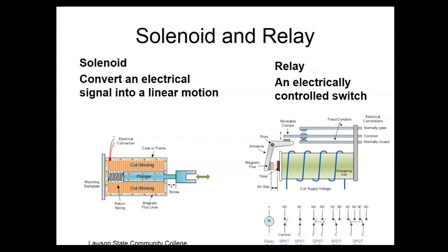So you have your fob that you carry around. You don't have a key. You just have something you carry around in your pocket, and then when you get in your car, you press a button, and the thing starts. Well, the starter is pulling quite a bit of amps, hundreds of amps to start that car, that you're not doing that. So what you're doing is your push button is energizing a relay, and then your relay is closing contacts that are connected to the relay. So this is all done by magnetics, and we'll show y'all these when we come into campus.